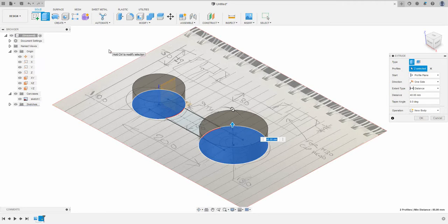mid-tolerance. Fusion hasn't got the ability to work with tolerances until you get to drawings, 2D drawings, but for a CNC machinist we want to make sure that the actual model itself is at mid-tolerance, so that when we do machine this, then what we are machining is at mid-tolerance on the CNC machine. So I could put 50 in, but that's at one end of the tolerance, and that gives us a problem when we come to machine, because it could be out of tolerance when it comes to be inspected. So in this case I'm going to put it in at 49.5.